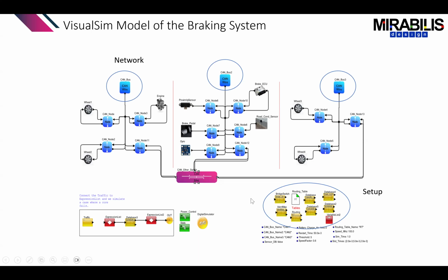Are we using CAN, CAN-FD, CAN-XL? Are we doing any power management within the CAN buses? Then what happens to the gateway? How do I connect these different segments through this gateway? How much are the ingress and egress buffers? What kind of bandwidth do I need to allocate for each data stream or traffic stream? Looking at all of those at the gateway level.